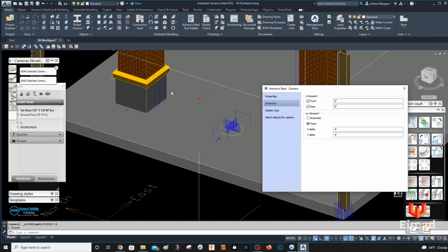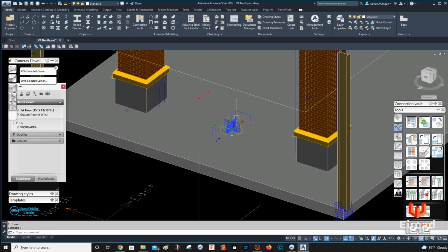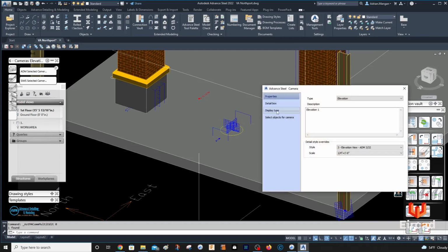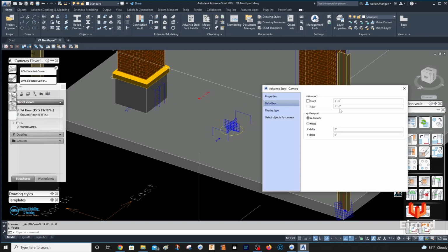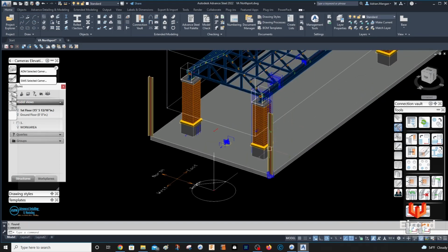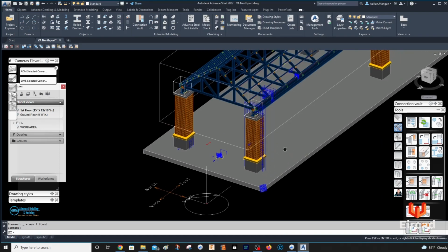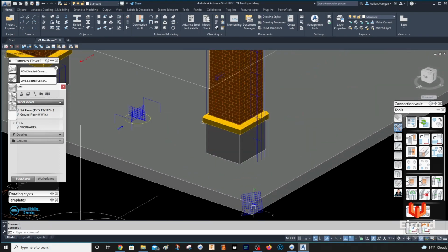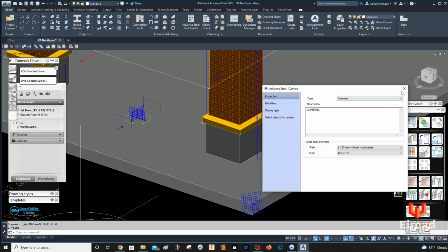So it's one for the base plate. This one here, detail box, is automatic, so it's running through the whole project. No front view, so it's unlimited both directions. So you can unlimit them. Automatic means everything that's in that view will be given on a sheet. Let me delete these two columns that I don't need anyway, or that might mess up something. This one here is also a 3D view, an isometric.